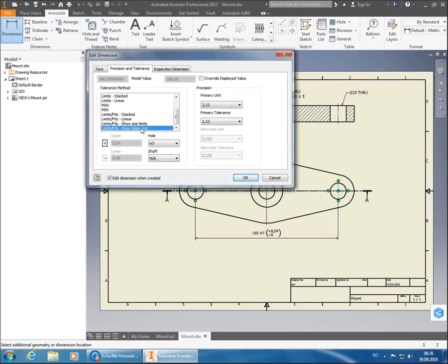And it's also going to show us what the tolerance is going to be in millimeters. And for the ISO fits, they usually have 3 digits, so point and then 3 digits. And then it can be wise to do the primary tolerance part up here and set it to show 3 digits. Because now,